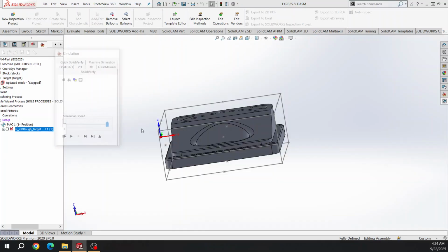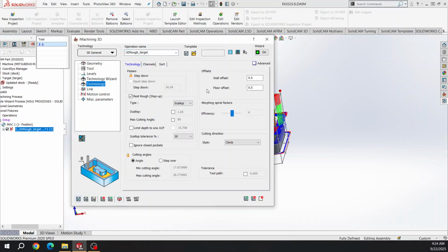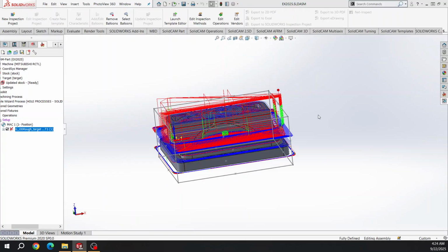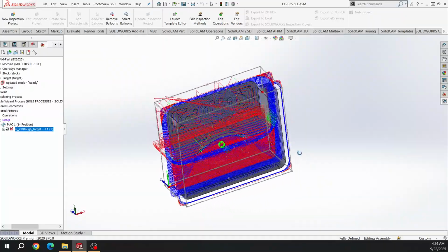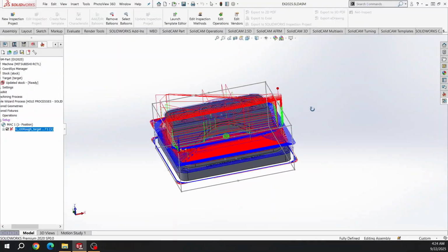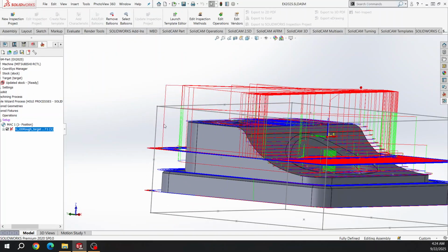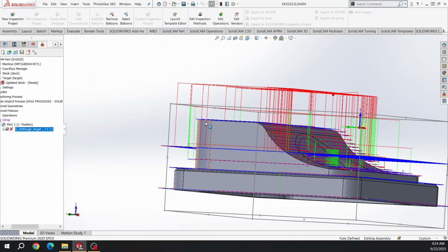So then what you have to do is, let me exit from this one. You can see how the tool path is going. Completely different way of machining. And again you can see how much depth the first cut goes, all the way to like 50 millimeters. Remember the cutting length is 50. So it utilizes most of the cutting surface of the tool for this kind of operation.